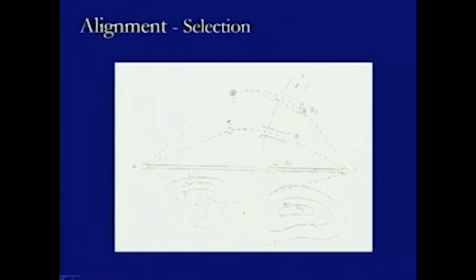But again, in these two cases there is further difference. What we found is that this is being connected with C, and then there is a very small curvature by which the road comes to this bridge and it becomes almost straight at this location and passes it, and then again there is a curvature by which it reaches this location B. Whereas if we look at this one, the connectivity from this point to this point D is straight, but after that a curvature is provided, and due to this curvature the widening has to be provided at this location, that is the bridge.